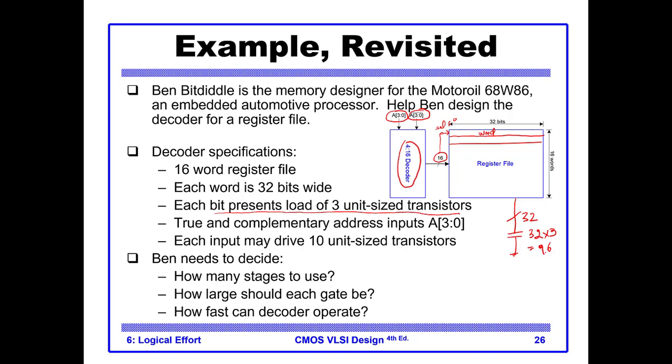True and complementary input addresses. Each input drives 10 unit size transistors. So if I take, let's say, A0, looking into this decoder, it drives 10 C capacitance.